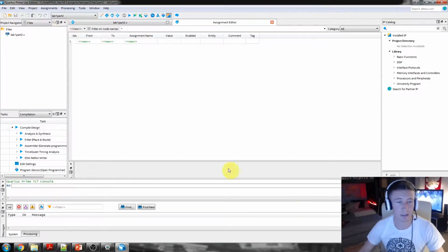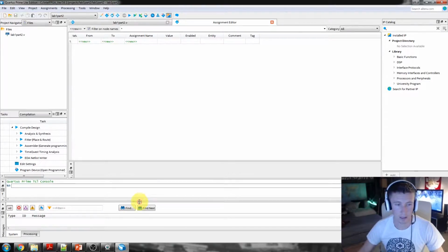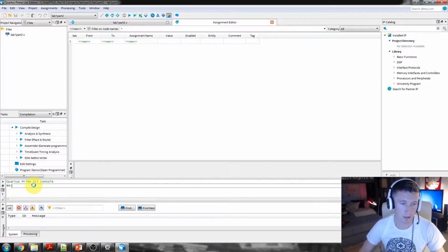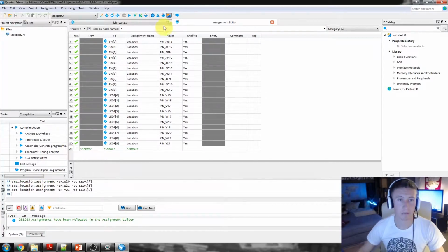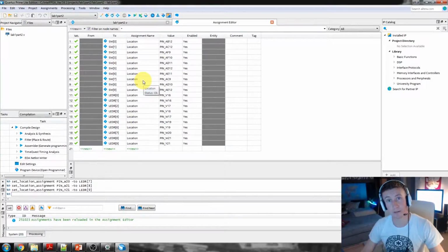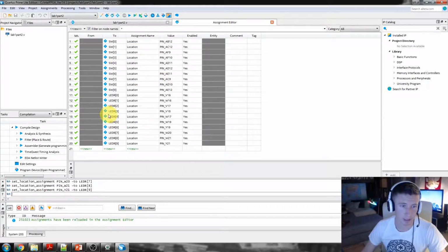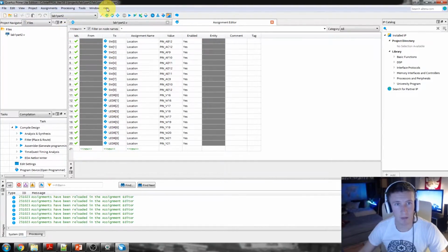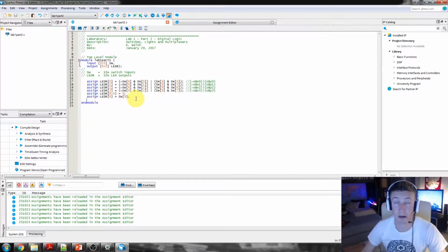So we're going to use our Tcl Console, and I have these already ready to go from my .qsf file, which is your Quartus settings file. Okay, boom. If you're wondering how I had all these already, maybe go back to the previous video. We had a couple of different ways to prepare these files. So all right, we have all of our pin assignments done. So we should be ready to compile.